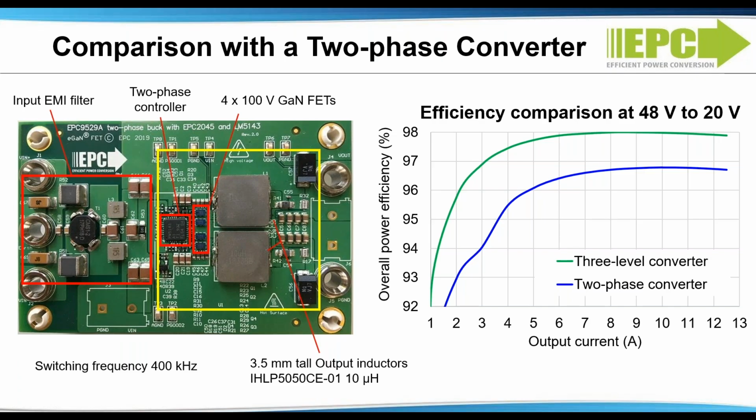And in the case of the multi-level converter, one driver is used for the lower two FETs, and then one driver, high side only, each is used for the two upper FETs. We also have a how-to app note on that one. And Renee, what's the name of it? How to build an ultra-thin multi-level converter, something like that. It's available on our website.